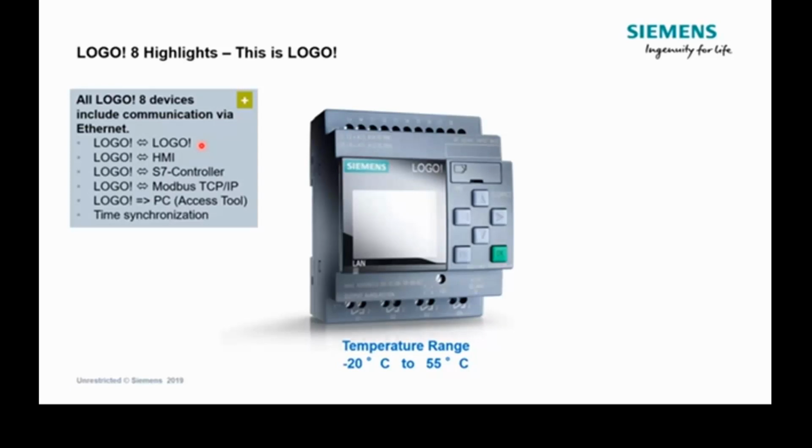So we can initiate this style of communication with a single Logo as a master and then a further 8 subordinate slave devices. So they're the same physical piece of hardware, but through the menu we activate the slave mode on the Logo. And that means it doesn't run a user program, but we have direct access to its inputs and its outputs of the base module and its expansion over the Ethernet network back to the main controller. And we can have up to 8 slaves on the network.